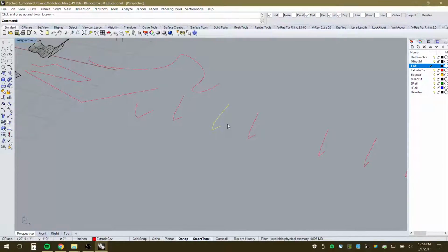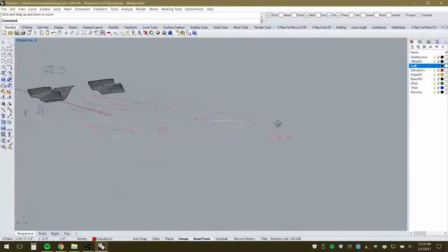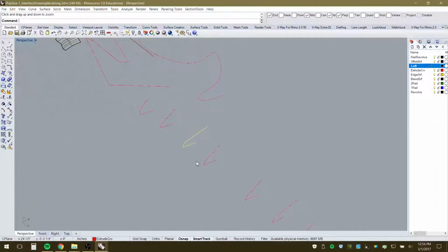That's also, I believe, a shortcut that you can get to if I hold my control key down and right click, I can get to that in the orthographic view. So I'm holding control and then right clicking, and then that'll give me this kind of smoother zoom. Again, right click without that in this perspective view is going to be orbit. And right now, because I zoomed into it, the view is orbiting around that particular object.